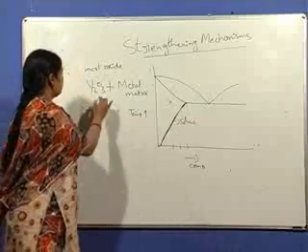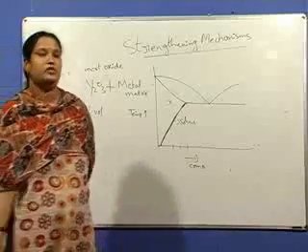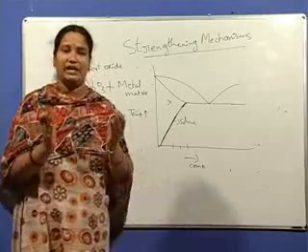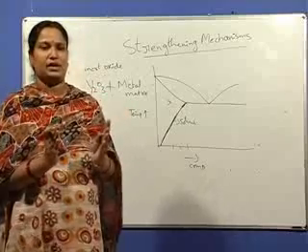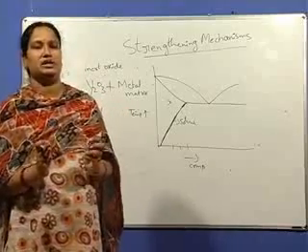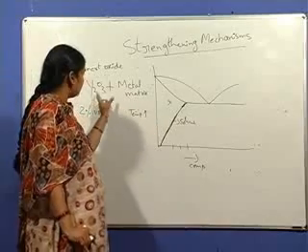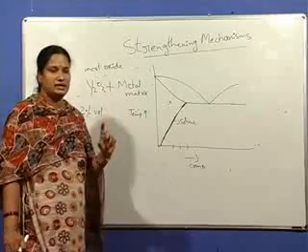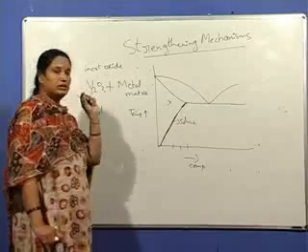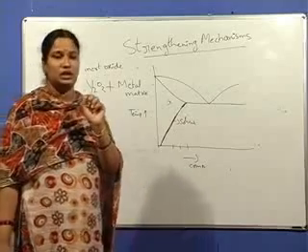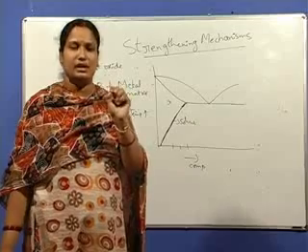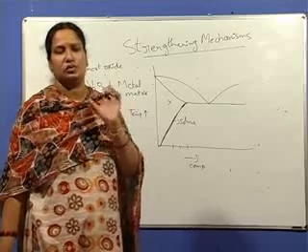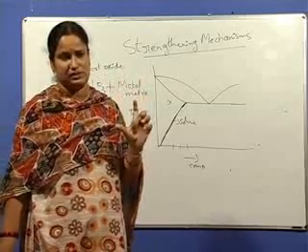The size of this yttria is less than 25 micrometers. They are mixed in a high energy ball mill, and they are consolidated and compacted by powder metallurgical techniques. Since this oxide is inert with respect to the metal matrix, even at higher temperatures the dispersoids do not undergo coarsening. They undergo only a very small extent of coarsening even at very high temperatures.